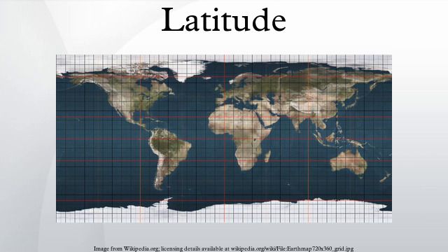Auxiliary latitudes. There are 6 auxiliary latitudes that have applications to special problems in geodesy, geophysics and the theory of map projections. Geocentric latitude, reduced latitude, rectifying latitude, authalic latitude, conformal latitude, isometric latitude. The definitions given in this section all relate to locations on the reference ellipsoid, but the first 2 auxiliary latitudes, like the geodetic latitude, can be extended to define a 3-dimensional geographic coordinate system as discussed below. The remaining latitudes are not used in this way.